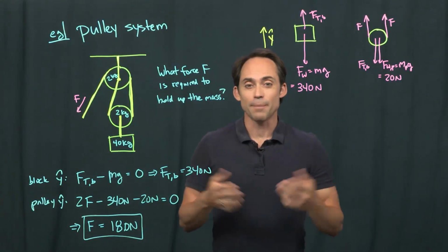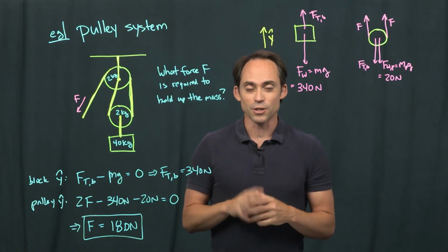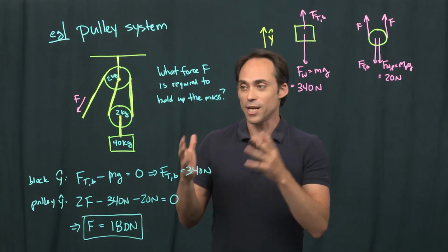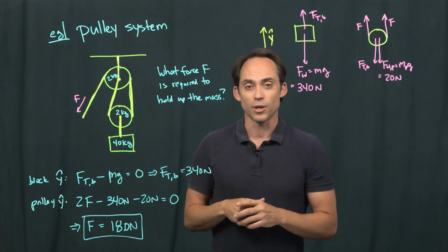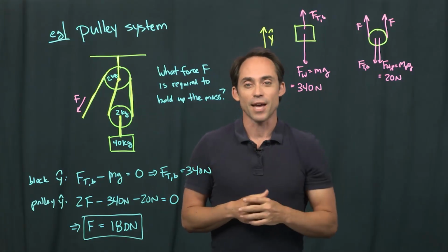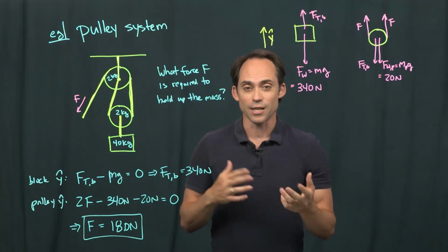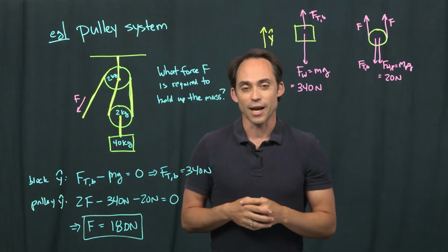So we've seen a few examples of statics problems, and hopefully you remember how to set up the problem so you can solve all sorts of different variations. But the main steps are looking at your system, setting up the force diagrams for all the important components. All right, so we have some examples of that here. And applying all the forces, just as we've done looking at different force diagrams, making sure you go through your system of forces and that they're all on our diagrams.